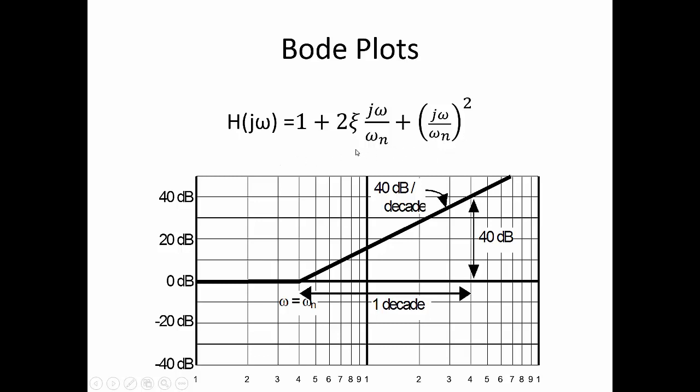If the complex roots come in the numerator, again, do not factor. Rewrite it with a 1 in the front, and make sure you square whatever you have for your coefficient for j omega.